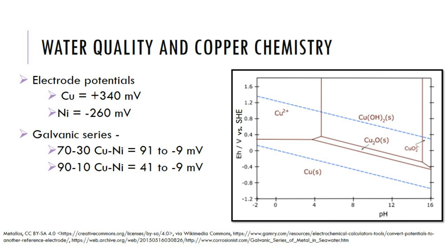If we take the example of the galvanic series, it is not really applicable to the Pourbaix diagram, but I would just like to take the example because here also the copper is the element which will form the compounds when corrosion occurs for these alloys.